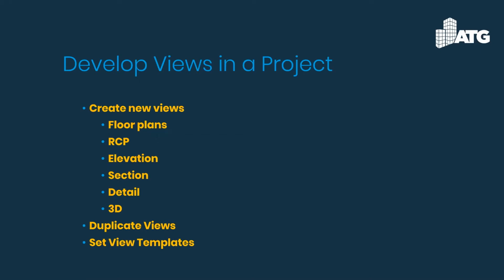A couple other things is adding phasing or adding design options to it. Typically those things you want to kind of hold off on until you start the project. Those aren't typically items that you can have pre-created, because you don't always know what the phasing is going to involve, or also the design options and what kind of options are going to be set for a particular project.